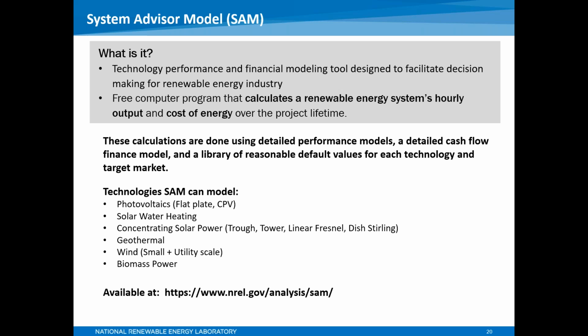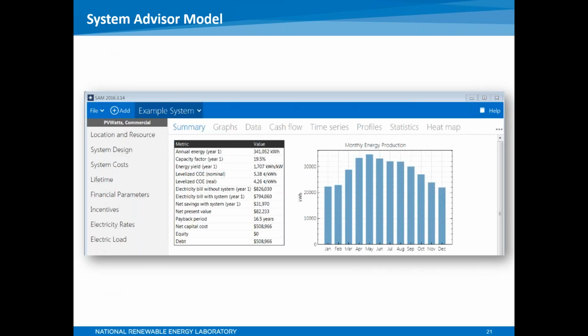It also has some good default inputs, so it can let you do an initial pass, and then maybe you can refine the analysis a little bit more. It's a technology, performance, and financial modeling tool. So that might be something you want to turn to after you've run PV Watts and said, well, this is still looking really good. Let's do one more step with this and look at the System Advisor Model to see how things are looking. And here's just an example of the reporting that you might find from SAM.